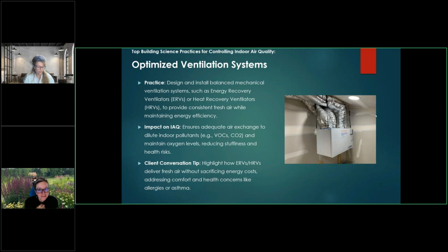You've got to remember that you've got exhaust from a kitchen hood, exhaust from your clothes dryer, exhaust from a bathroom. Depending on what you use for ERV strategies for those, typically homes are going to be under negative pressure. You're just providing makeup air for whatever you're exhausting. That's what's balanced in a humid or mixed humid climate. Even with an ERV, you're typically going to want to set it so that you're bringing in more outdoor air than you are exhausting, to try to get a slight positive pressure if possible in that house.